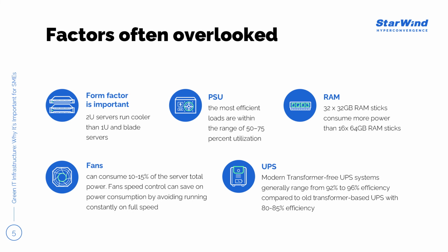For example, an uninterruptible power supply unit with a 95% efficiency rating will have 95% of the original input power in the load and connected systems, with the remaining 5% basically spent, or wasted, if you will, running the UPS itself.